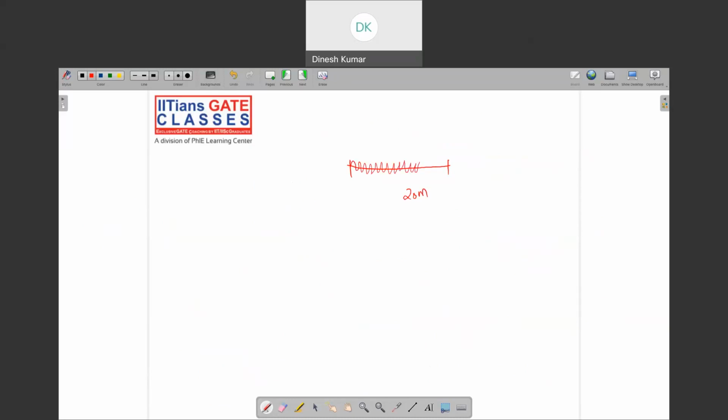Right. So 66 total sine waves will actually be present here now. That means if you take this point, the voltage at this instant is this, at this instant is this. So at every point the voltage, or the current, is different. That means we cannot lump everything together, because the same current is not flowing through all of them, right? So that's why we are considering a distributed system. So it all depends on the frequency.